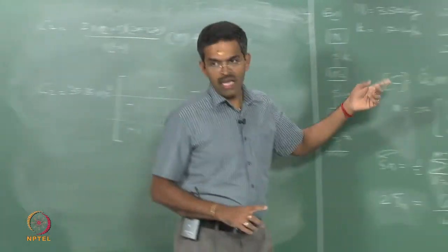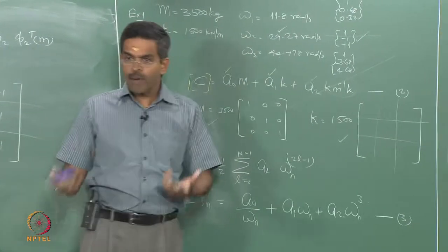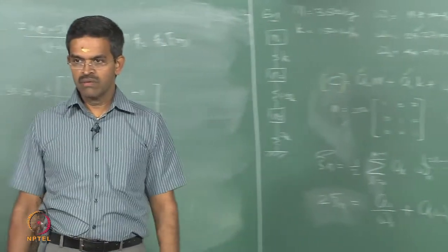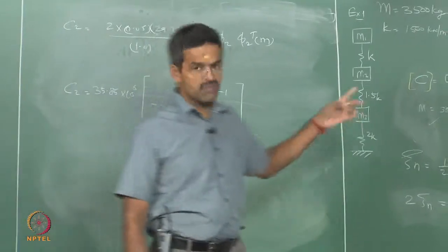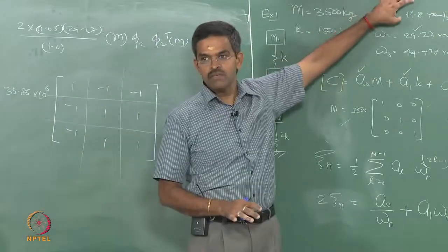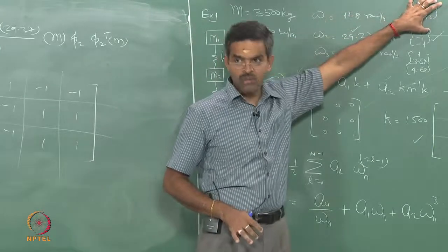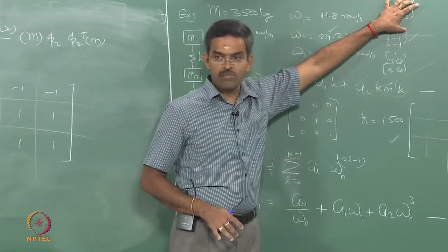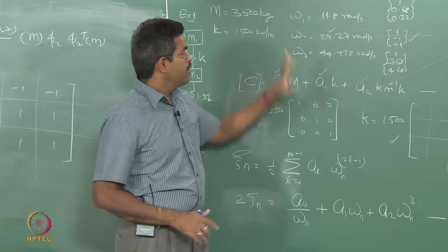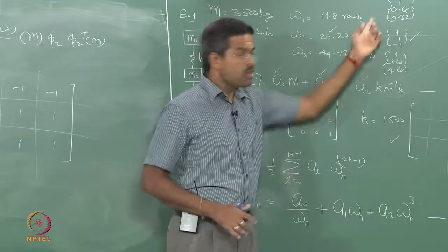Therefore, the classical eigensolver which will give me all the mode shapes and all the frequencies is unpopular. And it is because of this Dunkerley is more popular, because Dunkerley at least for sure gives me the fundamental frequency. Stodola is popular because it gives me the fundamental and the mode shape also. The influence coefficient method is popular because it gives me the frequencies and mode shapes in order and they are orthogonal automatically.